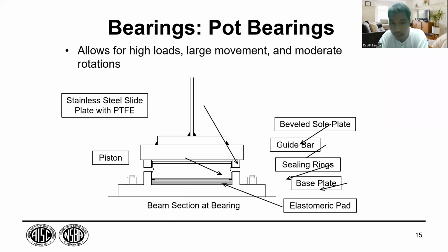Pot bearings, guys. Remember pot bearings, like this? Okay, pot bearing. Stainless steel slide plate with PTFE. PTFE is plastic, a very hard type of plastic. Okay, allows for high loads, large movement, and moderate rotation. Beveled sole plate. Okay, so this one is the beveled sole plate.